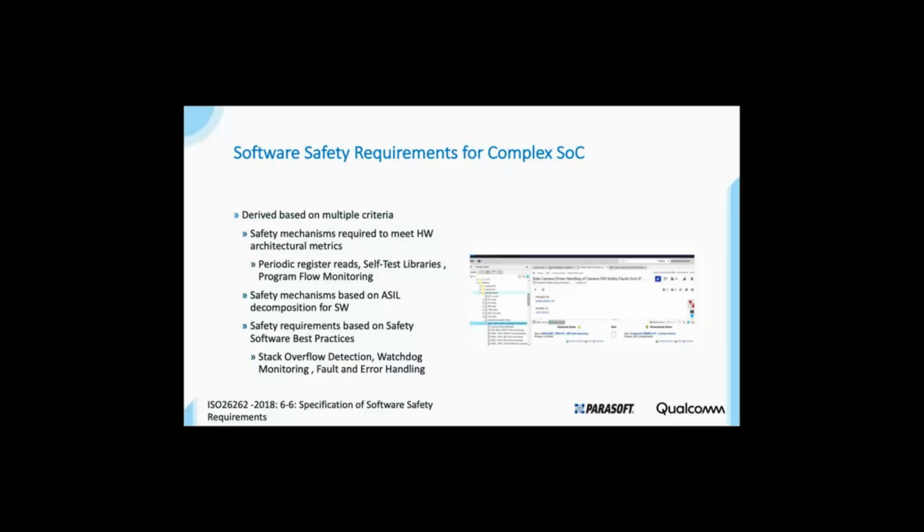And the next one, as I talked a little bit earlier, is based on ASIL decomposition. So even though most of our requirements are ASIL B or ASIL D, we went and looked at each requirement, worked with the individual software teams, and checked if there is a way to do ASIL decomposition so that we don't have to necessarily develop higher ASIL software. So this led to decomposed requirements to be able to develop components at a lower ASIL. So this is the second thing.